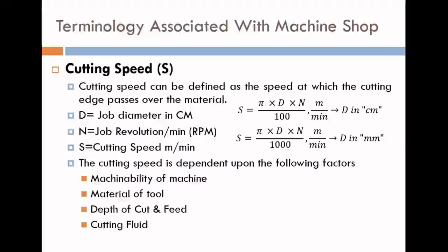If we use cast iron on the milling machine, then the required cutting speed is 50 meter per minute. Like this, a sheet with sets of materials, cutting speeds and machine setups is already present in industry.